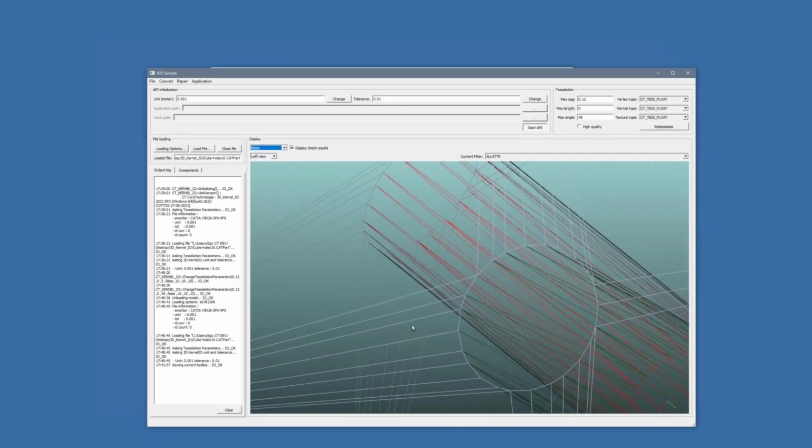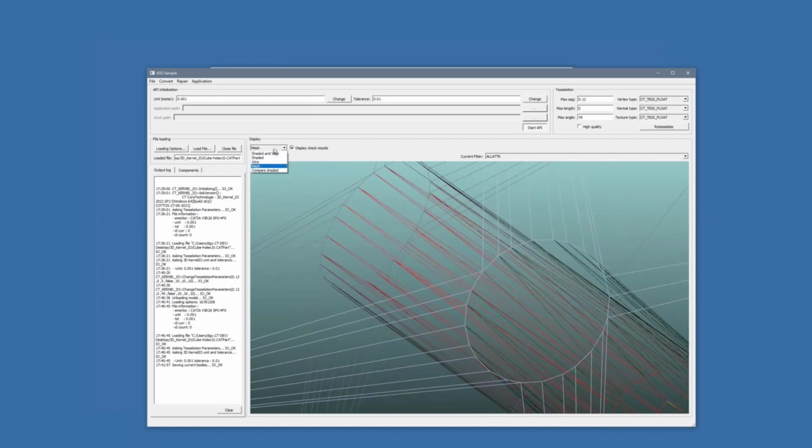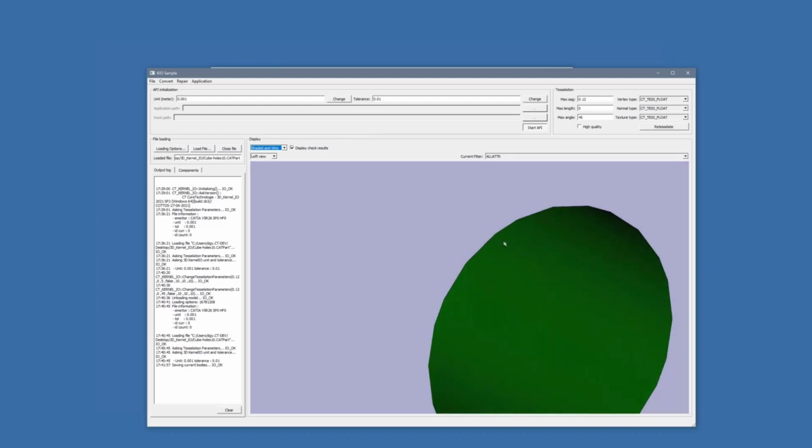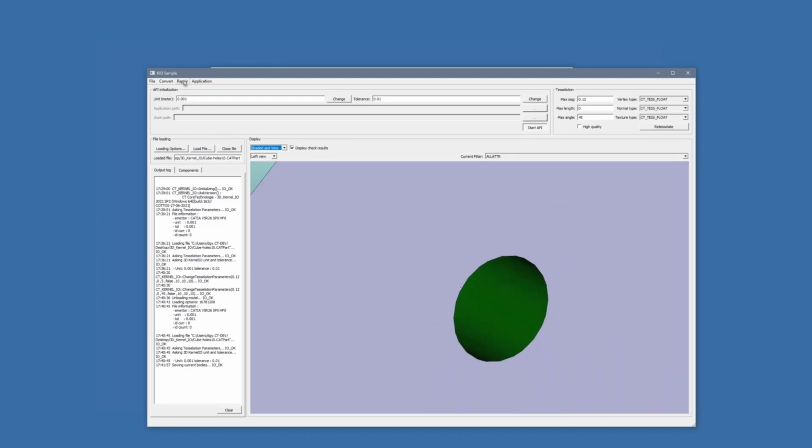So now I will ask 3D kernel IO to compute new triangles, which has been done automatically when I switched this. So I'm sorry, but now, as you can see, there is again a very nice tessellation. So we have some healing algorithms, stitching algorithms, sewing algorithms. If it's something you are interested in, you can ask us to do some specific demonstration.